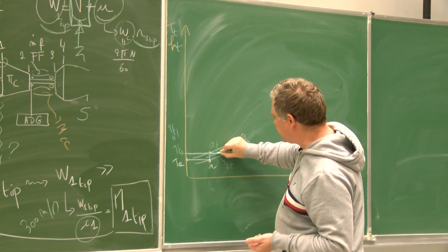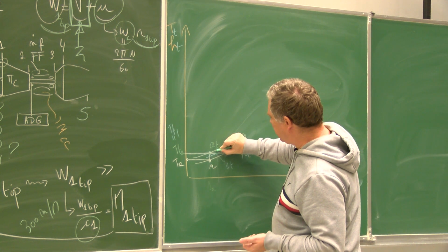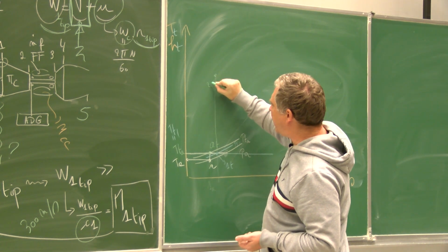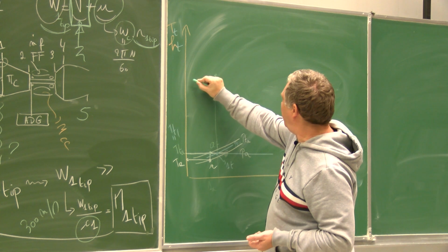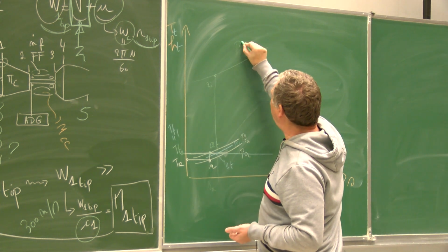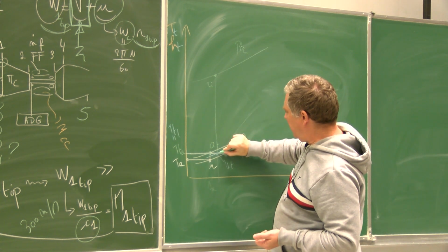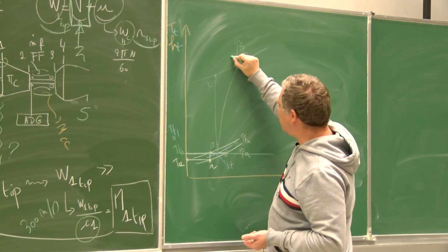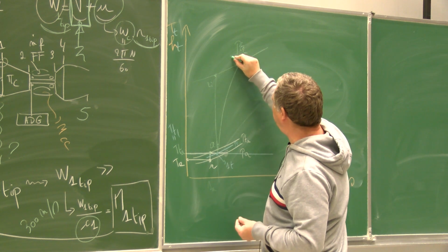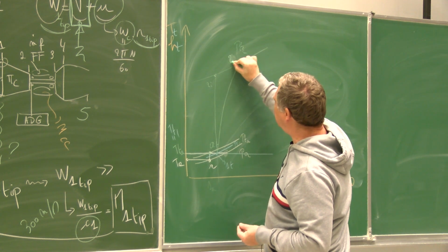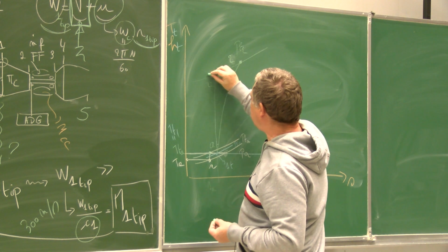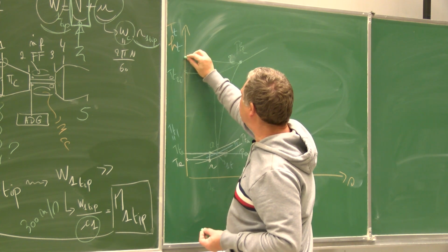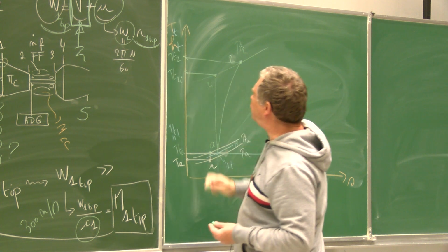And then you go into the compressor. So you start from this point, and you can go into the compressor isentropically. So you would have the point 2i, arriving on PT2, that is here. And if you are not changing isentropically, you would arrive in the point 2, that is here, with here the TT2i, and here with the value TT2.